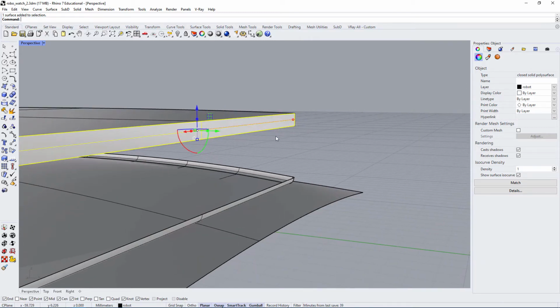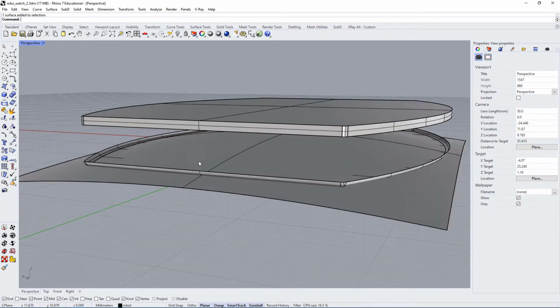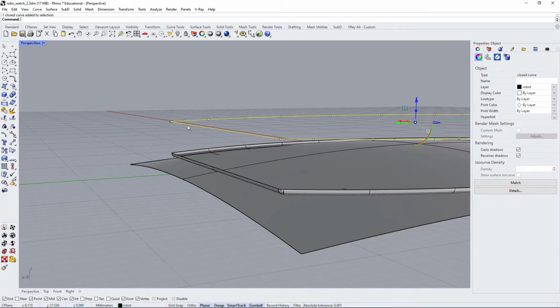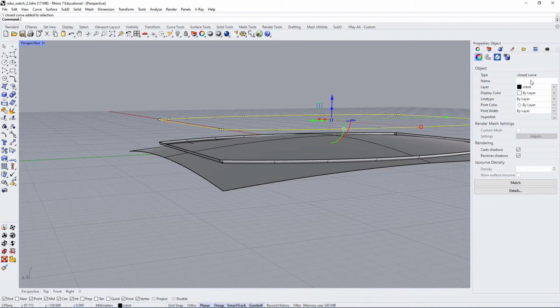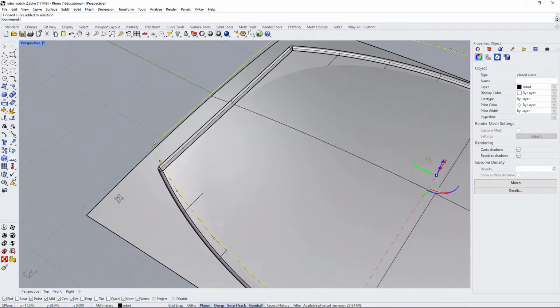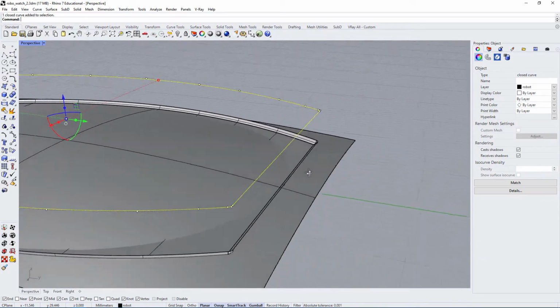Sometimes you see a single extrusion with a single edge, so a single starting point and a single end point, like a cylinder. You don't want that in this case. To avoid it, sometimes what you have to do is explode your curve so that it's not a closed curve, and then use that to cut an object. So that's something you could do. In this case, I think this should work pretty well.